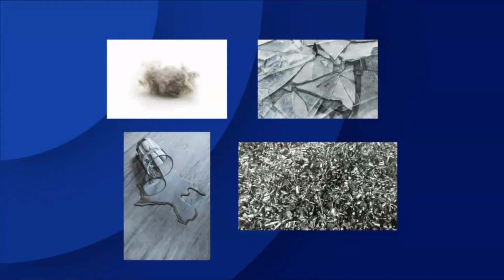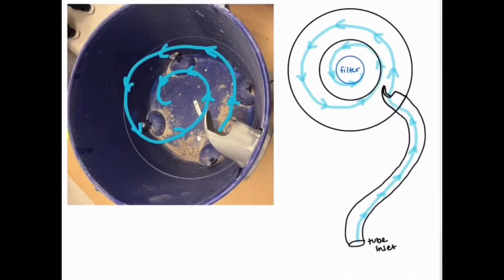Inside of this vacuum is a radial pump with a radial fan. During this video, we will explain how the fluid mechanics of the shop vac enable it to perform in the way that we want it to, by first considering the streamlines within the vacuum. Given that we are able to describe the flow through our shop vac as being steady, incompressible, as well as having a low Reynolds number, we are able to apply Bernoulli's equation with losses as we follow the flow along